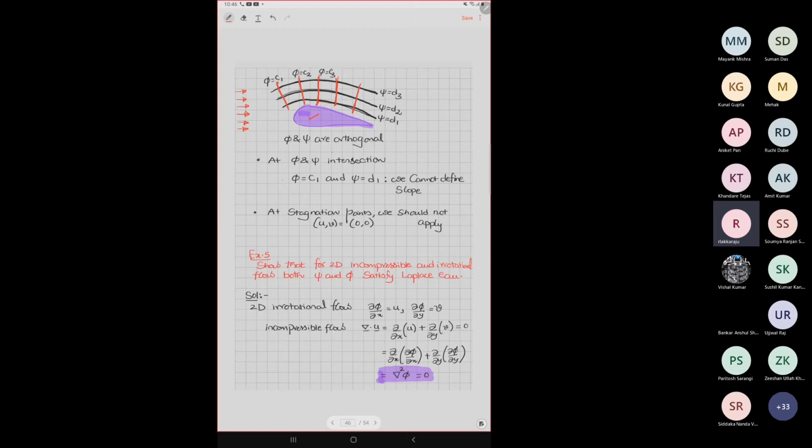At the phi and psi intersection, we cannot really define any slope. And these points in some sense are usually associated with stagnation points also. So this word again becomes important in our fluid mechanics. Stagnation point means your velocity field becomes 0. Maybe you take a plate, blow air or liquid. Liquid comes, goes along that plate, touches, is completely brought to rest, and again takes a turn. And it has an advantage in terms of measuring pressure.